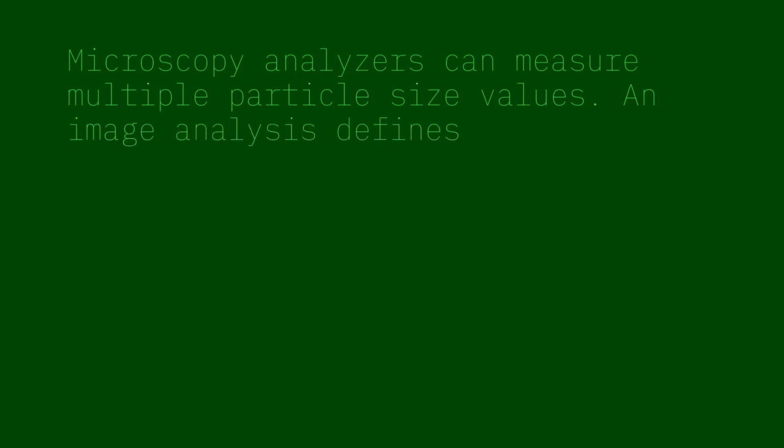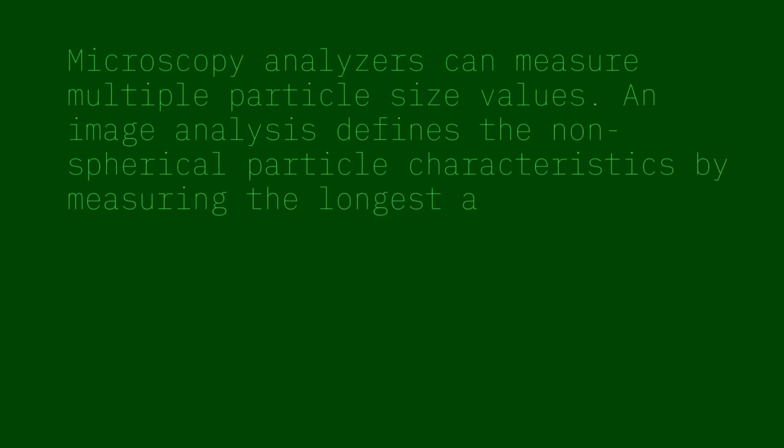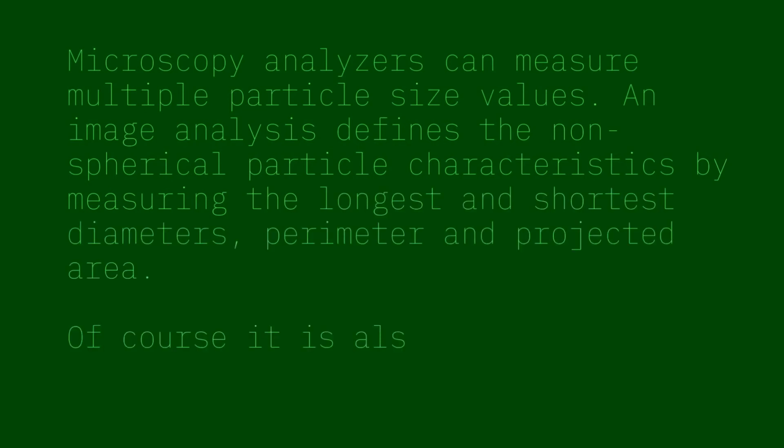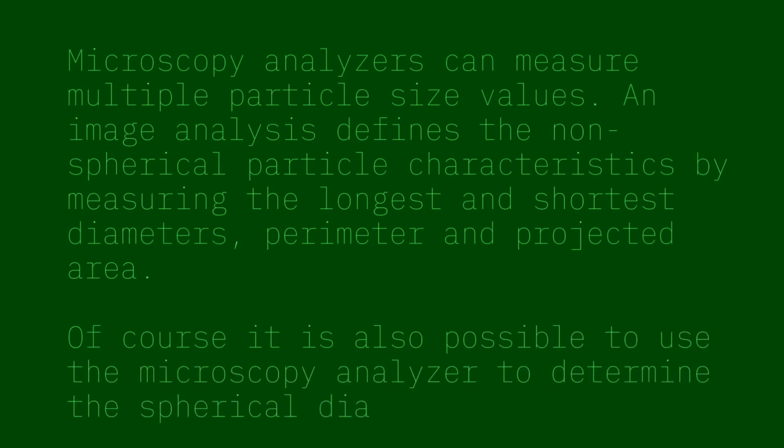Microscopy analyzers can measure multiple particle size values. An image analysis defines the non-spherical particle characteristics by measuring the longest and shortest diameters, perimeter and projected area. Of course, it is also possible to use the microscopy analyzer to determine the spherical diameter equivalent.